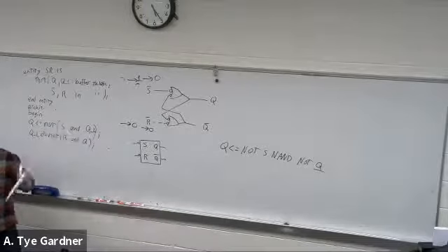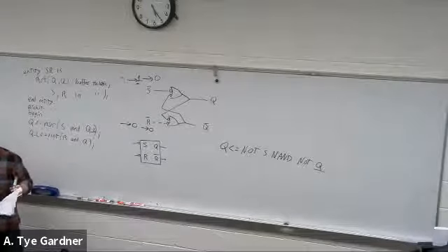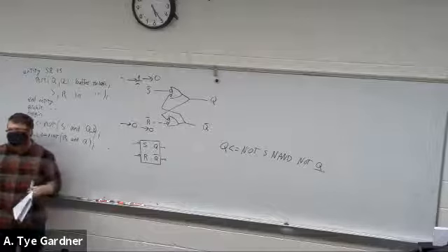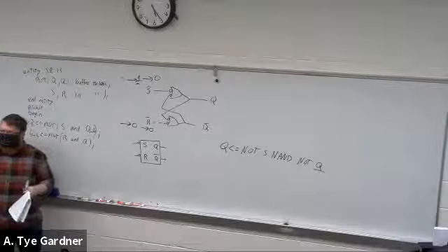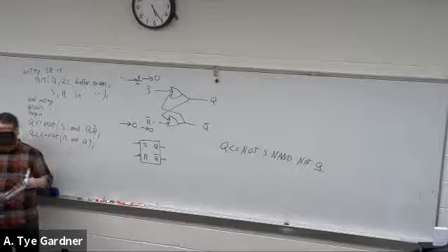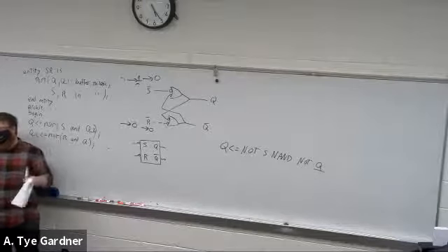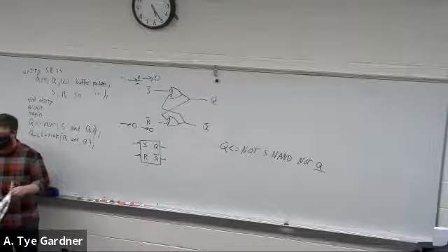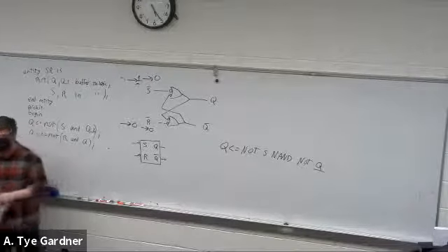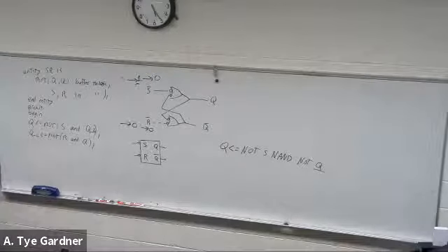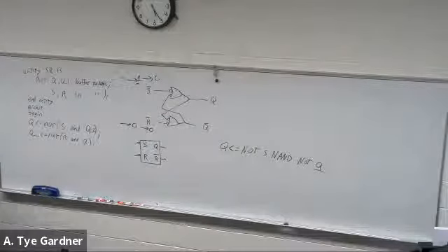Well, in a simulation, it would do kind of the same thing, except it gets worse, because at the fastest speed that it can, it goes, it's a 0, it's a 1, it's a 0, it's a 1, and then your computer locks up and crashes. That's practically what happens. So you want to be careful about set reset latches in simulation, because they will do that to you if you accidentally deassert them at the same time, and it's awful and annoying.